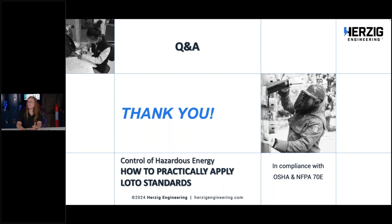Okay, for the electrical specifically, since that's what's brought up, it's about exposure. There are times where you're opening up equipment and you're not working on electrical, but the electrical components are exposed, 50 volts and greater. You're still within those hazard boundaries. So you would need to verify that it's off with the proper PPE before getting to work. If you can't do that, then technically you would have to keep the electrical PPE on until the work is completed. Now, mind you, that's whenever you're within the boundaries.